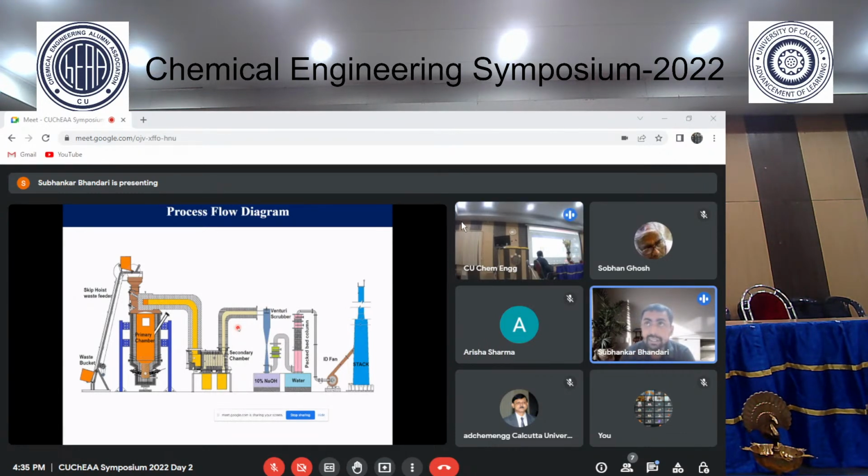In doing that, we avoid the formation of dioxin and furan. In the plasma chamber, dioxin and furan are disintegrated because of the high temperature. But at the downstream, the precursors of dioxin and furan may recombine and form dioxin. We mitigate that possibility by quenching suddenly from 1200 degrees Celsius to 100 degrees Celsius.